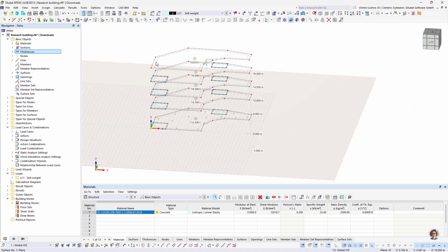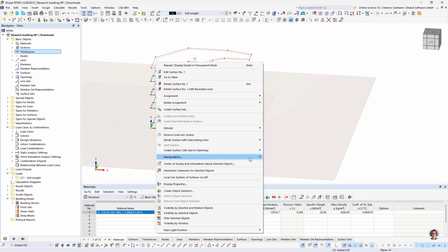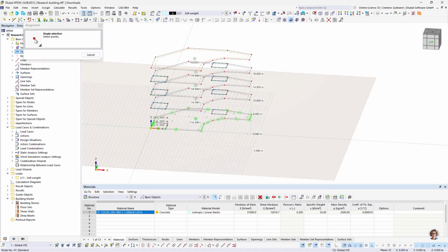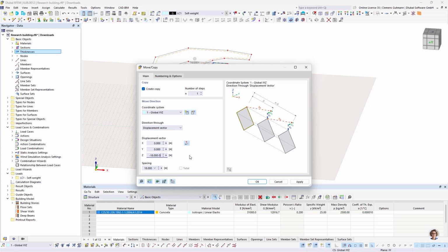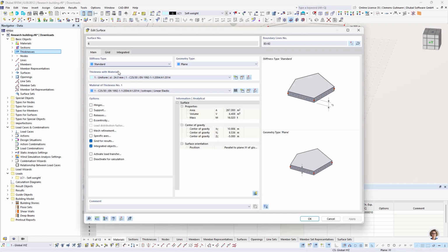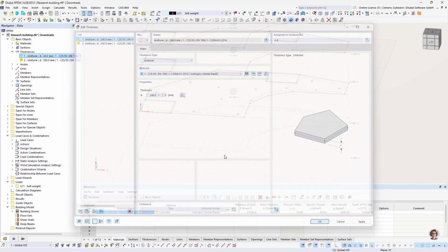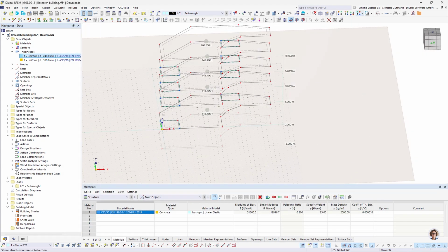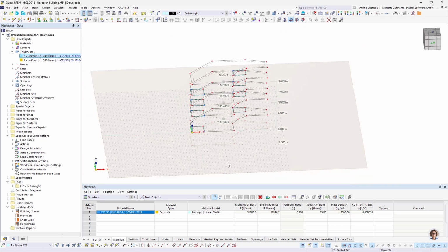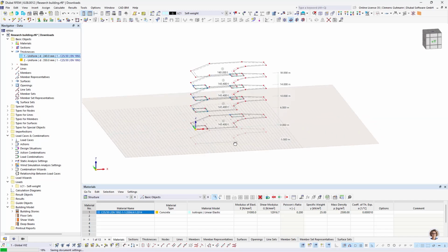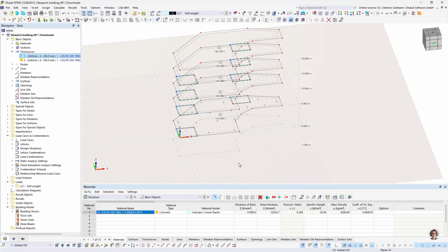I then want to create my basement. Therefore, I take the top floor, create a copy, and I have to add 5 more meters. Okay. And then switch the thickness to 35 centimeters. And I think I made a mistake here. Forgot 1 digit. All right. Good. So, by the way, this brownish thing is this terrain, that what we checked in the base data.